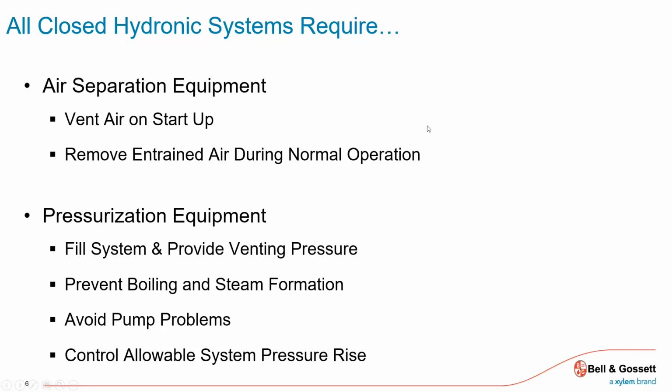Yeah, it should have. You would think it would have. But what Will's referring to is that cold water coming into the building. They want it to go through a check. It doesn't go back. Exactly. So originally that code didn't exist. So if the pressure in the system built and it just exceeded the street pressure, no problem. It just moved. And then eventually they say, hey, once the water's in your building, your apartment, I don't want it back on the main. So check it, put in a pressure backflow preventer.